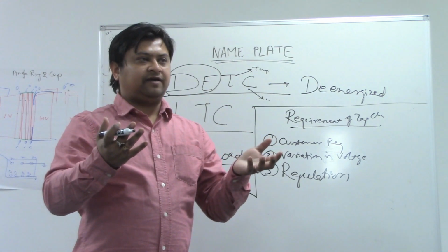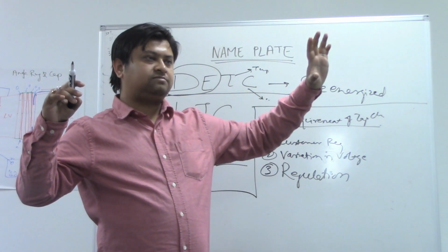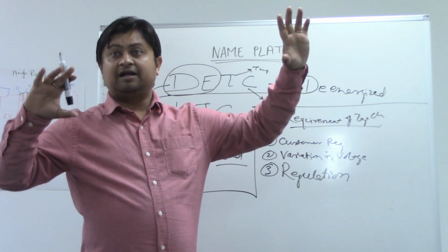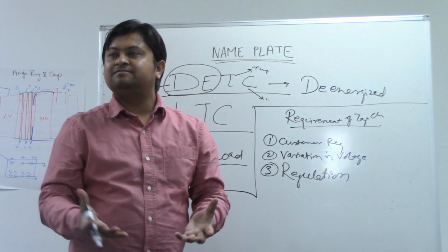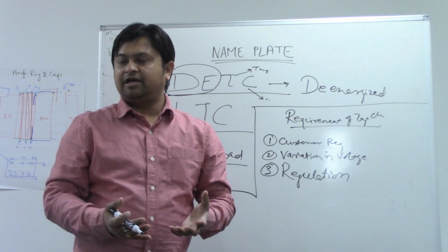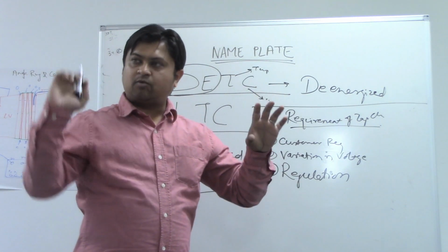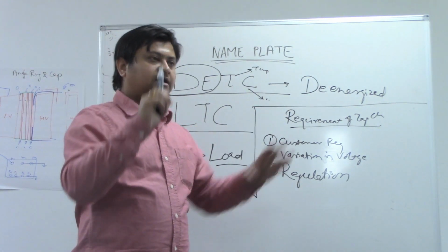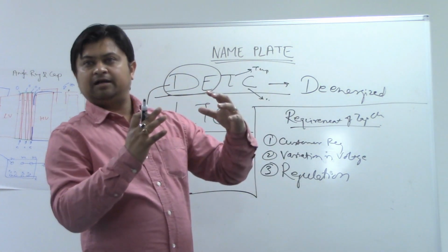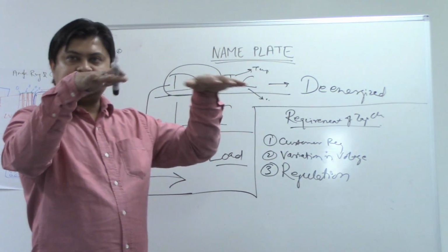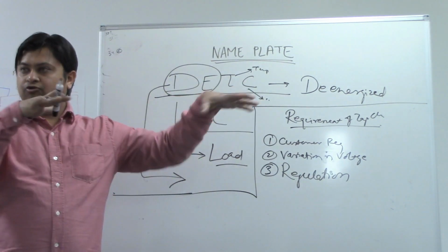On the other hand, if the requirement is 25.6 and the customer is supplying, say, 28 kV, then the equipment will see over voltage. That could again cause an equipment failure. So whatever voltage is required on the load side should be compensated from the transformer, so that there is a synchronization between the load and the load voltages.